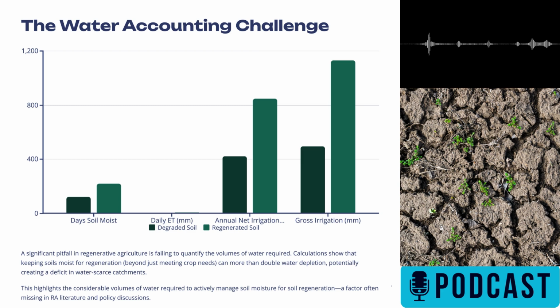And it's particularly important during prolonged rainfall. If that base infiltration rate is low, you can get surface ponding, waterlogging, which is bad for plants and soil life. Low oxygen.